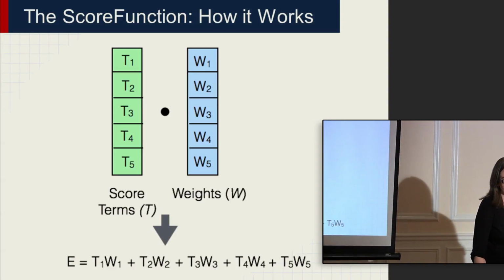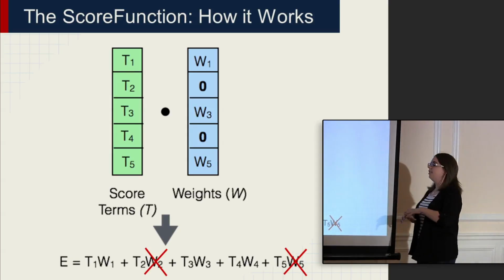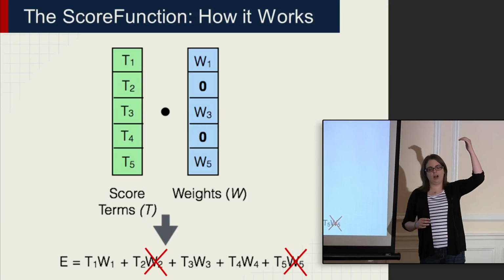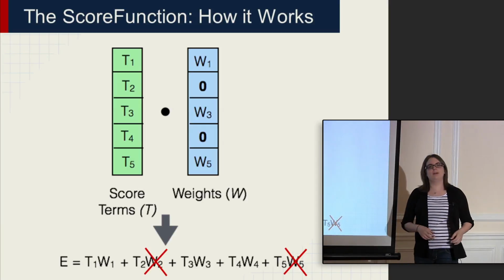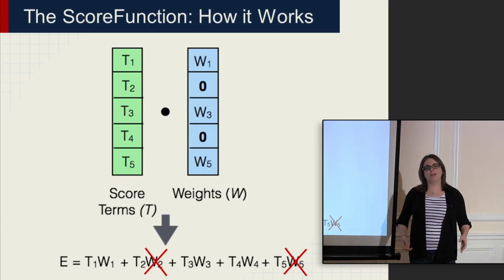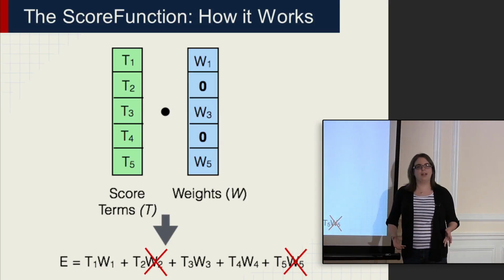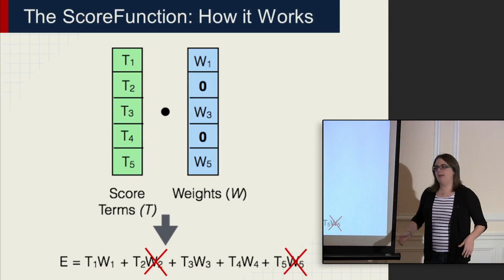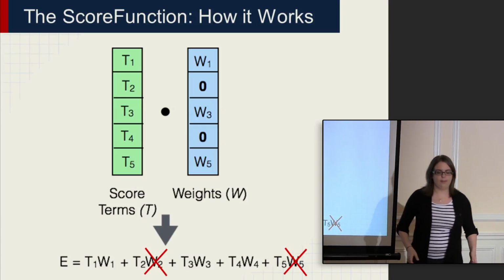What's interesting is that the ScoreFunction initializes all of the energy terms, but only evaluates the non-zero weighted ones. In this toy ScoreFunction, there are only 5 terms, but in Rosetta there are almost 200. So you only want to evaluate the terms that are relevant, and that can be done by specifying this in a weights file, which I'll talk about in a second.